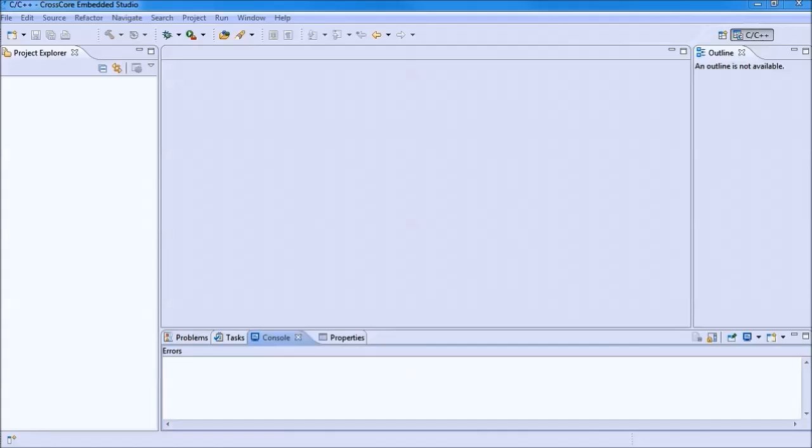This demonstration will take a simple audio talkthrough example from VisualDSP that makes use of the system services and device drivers, and provide a practical demonstration of the steps necessary to import this project into CrossCore Embedded Studio and make use of the SSL 2.0 API. The CrossCore Embedded Studio API is very different from the one in VisualDSP. Porting, however, is relatively straightforward.